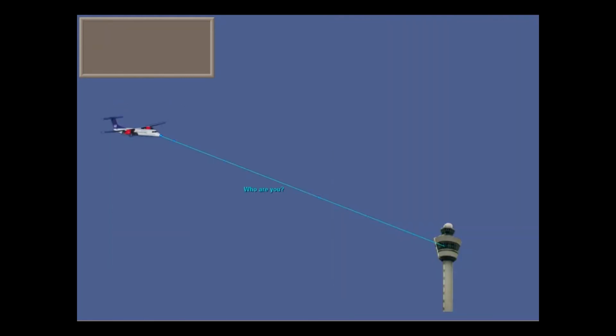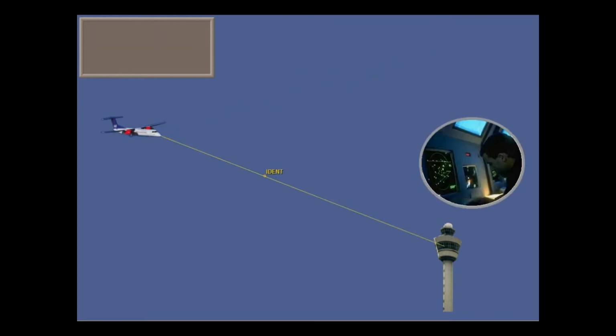The Mode S, which stands for surveillance, transponder system replies to interrogations from ATC ground stations by transmitting a signal to identify the aircraft and its altitude parameters. It also interrogates and replies to interrogations from other TCAS-equipped aircraft. Aircraft ident can also be squawked when requested by ATC to help them to find you on their screens.